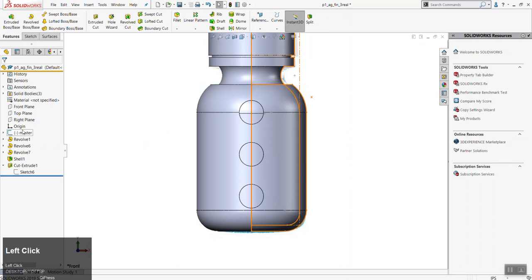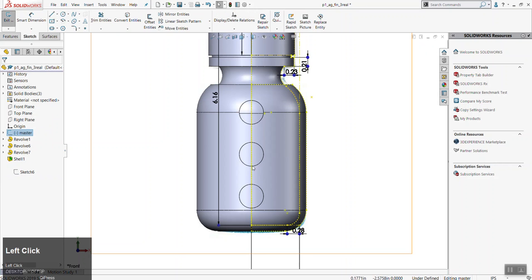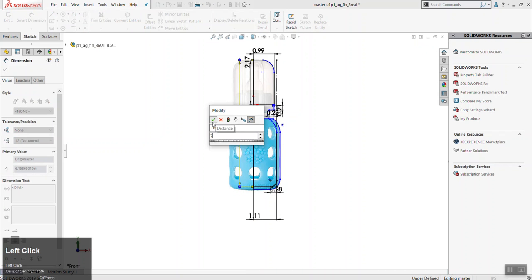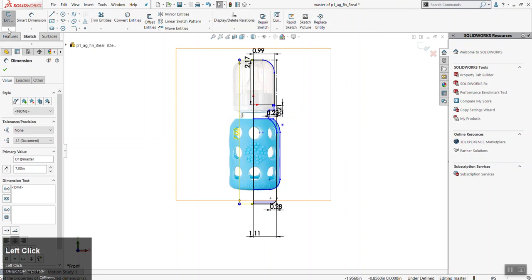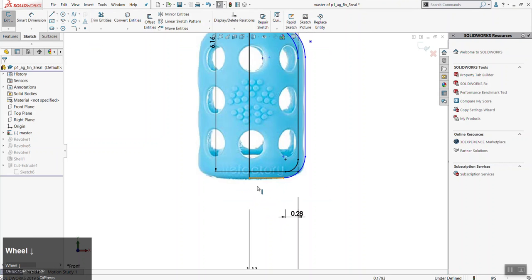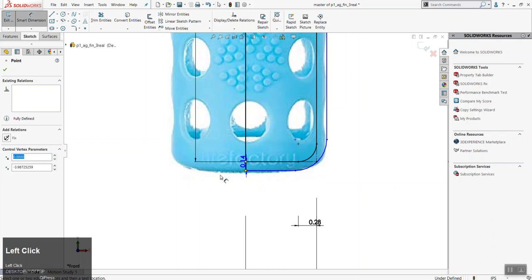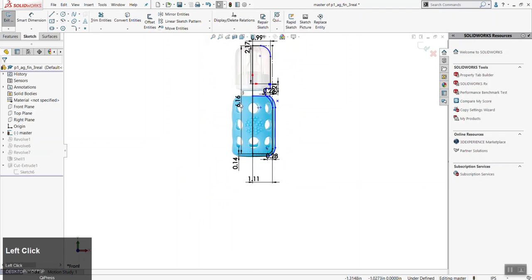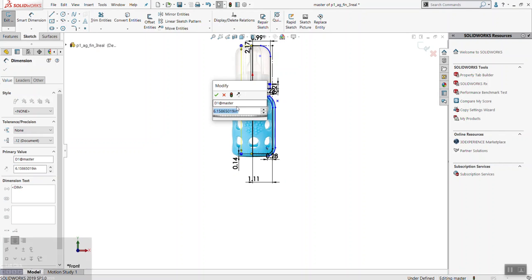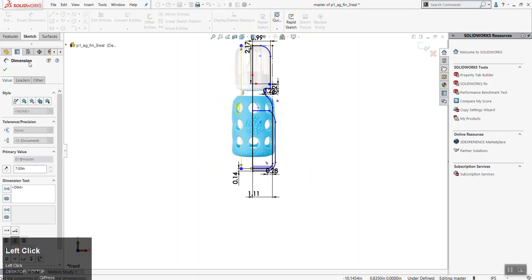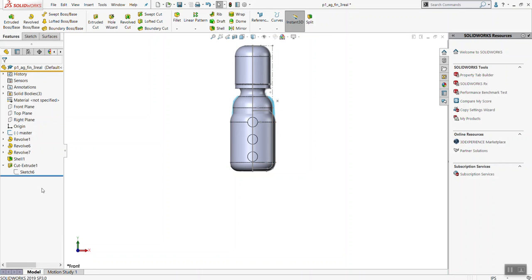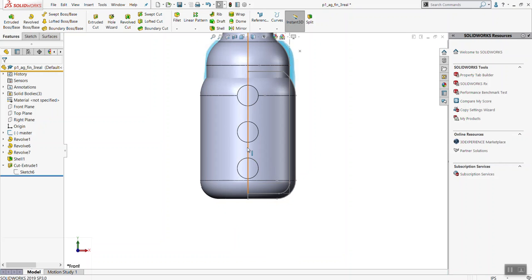Now if we exit this and change this master, let's see, that circle should rebuild with us. So let's hit 7 here. Oh, you know what? Here's the other error though, is you want to define this to this so that it moves with it. So now if I move this, we should see that those circles jump with us. So let's go to 7 inches, checkbox that, exit out. So it moved this here, but do you see how the circles move with it? Does that answer your question?